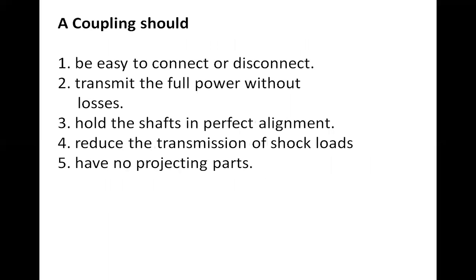A coupling should have some good qualities. It should be easy to connect or disconnect. It should transmit full power without losses. It should hold the shafts in perfect alignment. It should reduce the transmission of shock loads. It should not have any projected part which may be harmful or may create some problem in the machines. So these are the good things a particular coupling should have.